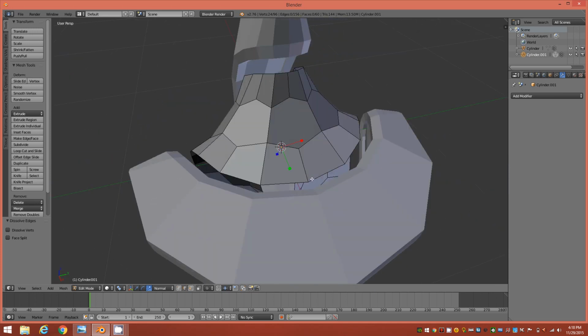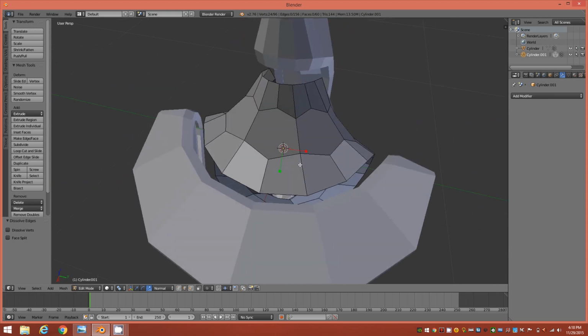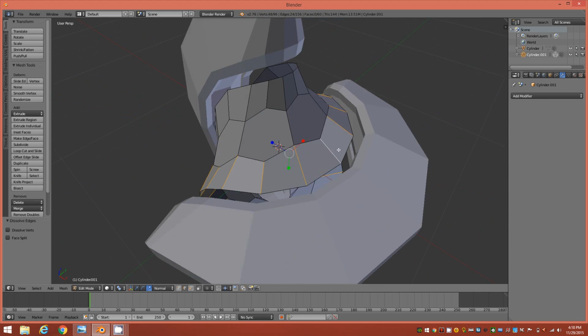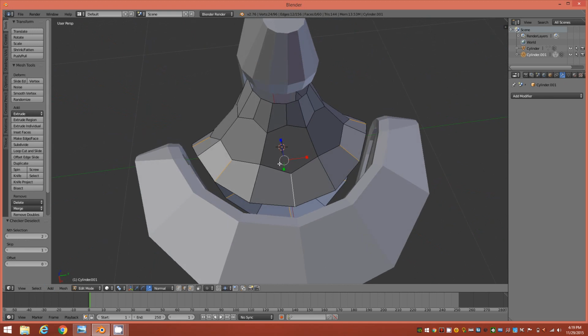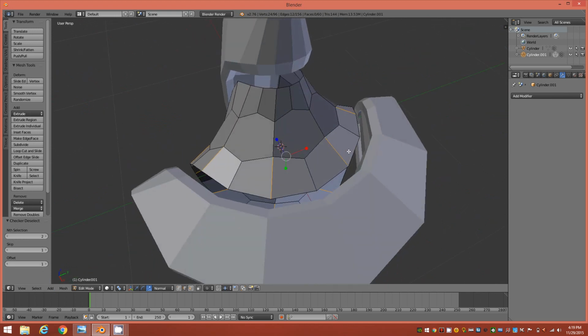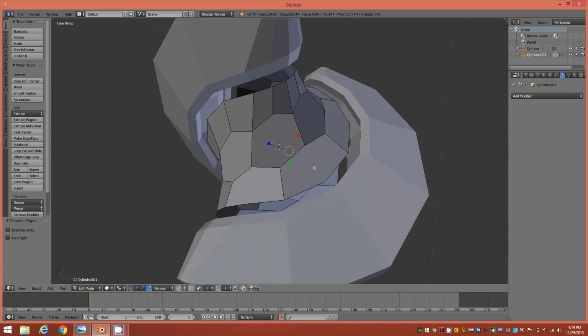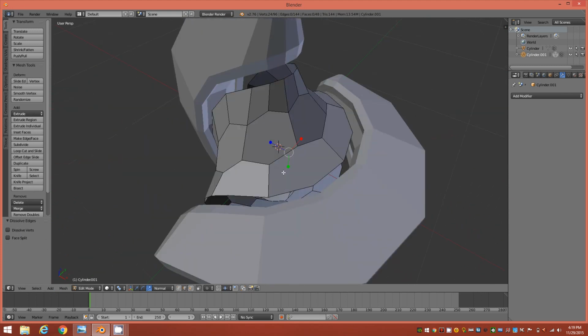We want to retain the vertices after we remove the edges, okay? So let's go ahead and select Control-Alt and select an edge on this edge ring. All right, and then we'll go ahead to select, checker deselect, and that gives us this selection, but we need to change the offset. So move the offset parameter just one place, and that will switch our selection type. All right, so this is what we want here. All right, and go ahead and X and dissolve the edges. All right, and make sure your dissolve verts is deselected. So then you should have something that looks like this.